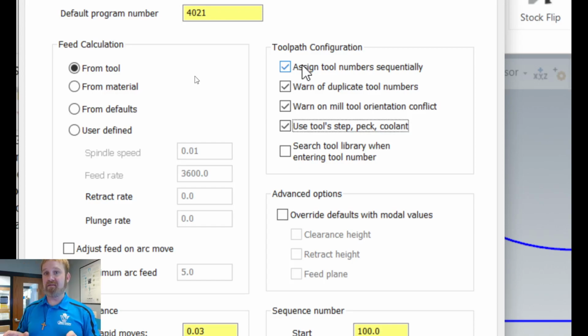And I say that because I get people that are like, oh, you can change these, it's okay. And they go changing them, and sometimes they don't get them right, and it really makes a mess out of the tool orientations and where everything's at, the station numbers. And then sometimes they change them and they don't change them back, and then the next person gets on there and something bad happens. Okay? We are not changing the tool numbers at the machine for the standard tools.